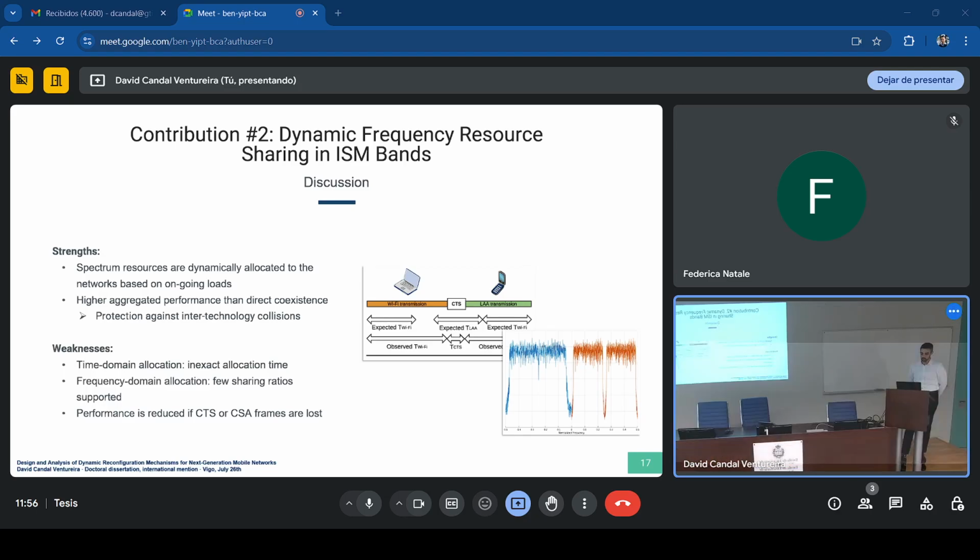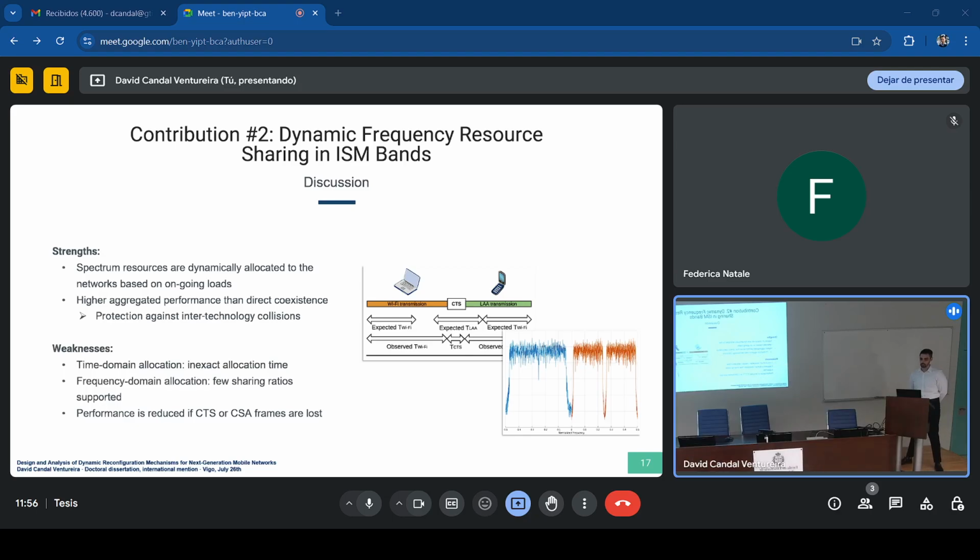It is also worth mentioning that our analytical model does not take into account that devices may decode signals below the threshold at which they detect the channel as idle, as I mentioned at the beginning of this chapter. We haven't done that because this mainly depends on how the devices are positioned in the environment and other environmental conditions such as propagation.